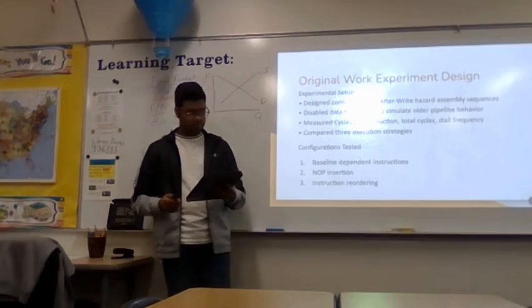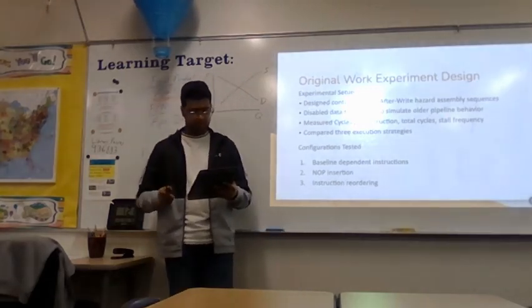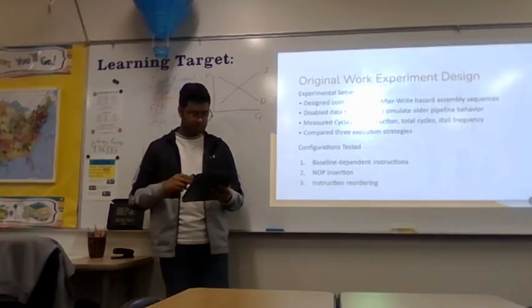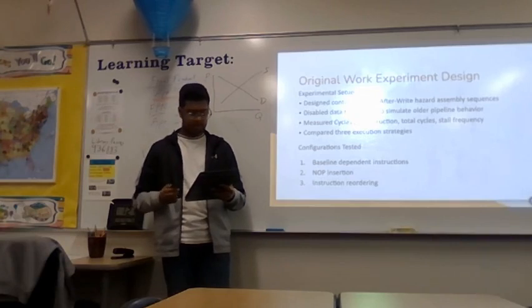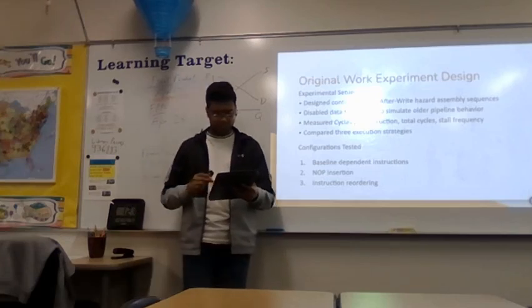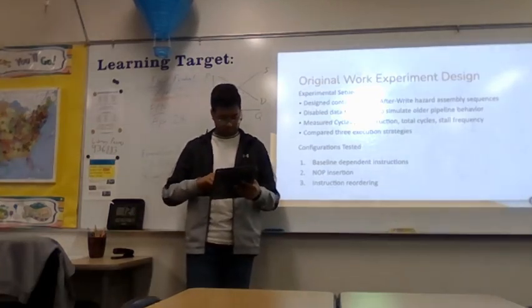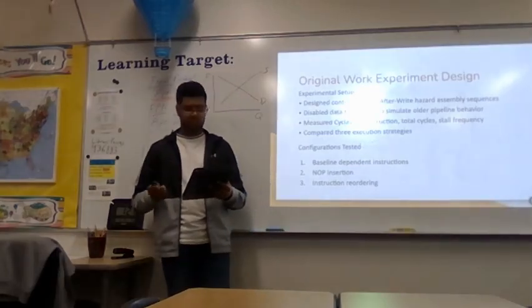For my original work's design, I created a controlled assembly program that deliberately created these RAW dependencies, and I disabled data forwarding in certain trials to simulate a constrained pipeline and make hazard penalties more visible. I wrote five assembly codes as microbench programs. Program one was intentionally inefficient.